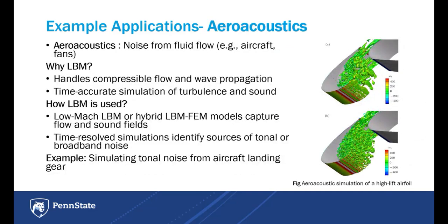The third major application is aeroacoustics, or flow-induced noise. Traditional CFD struggles with capturing the unsteady compressible behavior needed to simulate sound waves. LBM, particularly in low-Mach or hybrid forms, can accurately simulate both the turbulent source of the noise and the propagation of sound. This is very valuable in aircraft design, for example, when studying how landing gear generates tonal noise.